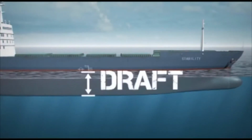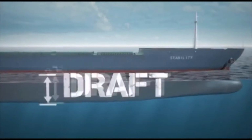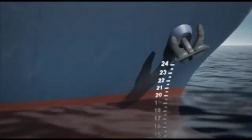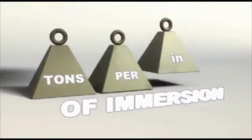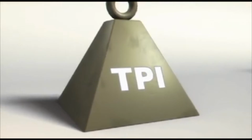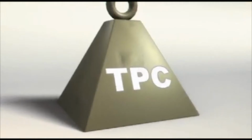Draft is the vertical distance between the waterline and the lowest point of the hull. A ship's draft can be found or taken by reading the draft marks that are welded onto a ship's hull, forward and aft. Tons per inch of immersion, or TPI, is the number of tons necessary to change the draft of a vessel by 1 inch. In the metric system, this is tons per centimeter of immersion, or TPC.